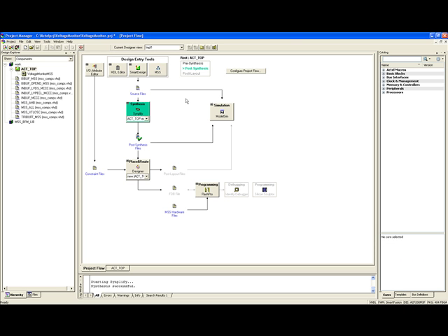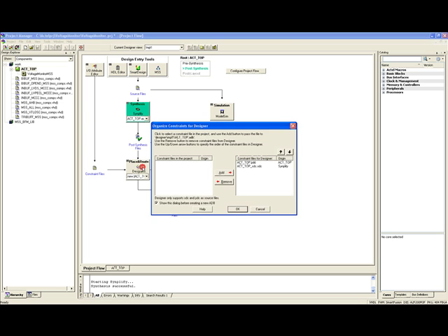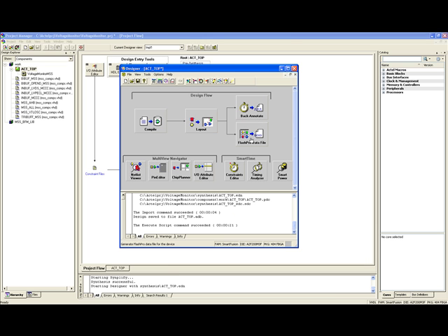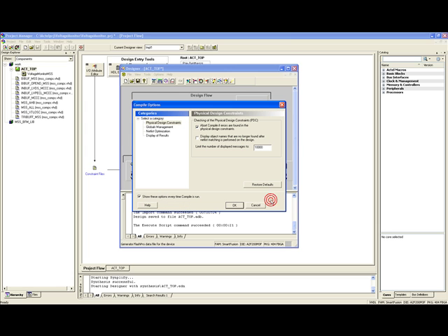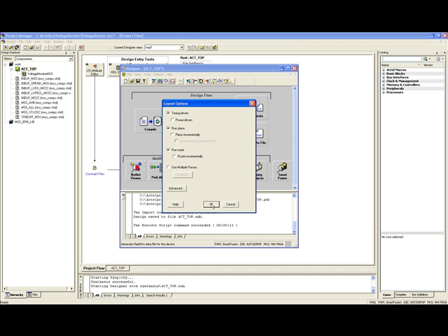Click the Place and Route button on the Libero IDE Project Manager Design Flow window, opening the Designer Organize Constraints dialog. Import the acetop.edn, acetop.pdc, and acetop.sdc files by clicking OK. Now, click the FlashPro Data button to start the compile, layout, and program file generation processes. Save and click OK on the various dialogues that open through the process.